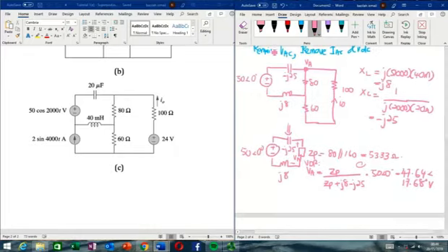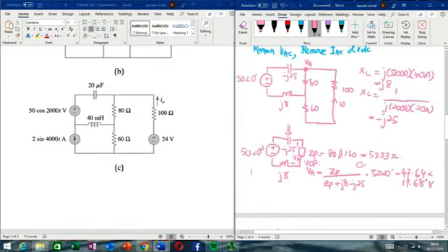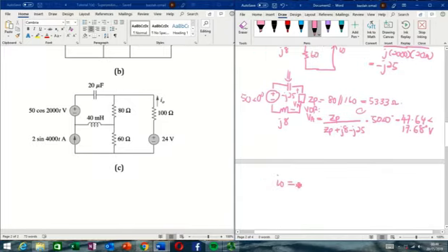Okay, so once we get the voltage at this node, it means that the voltage measured across the total of this resistance is equal to VA. To calculate I node, we can just use Ohm's law. I node is equal to, since the current that we are looking for is in the opposite direction, we have to negate the value. So negative VA divided by 160.